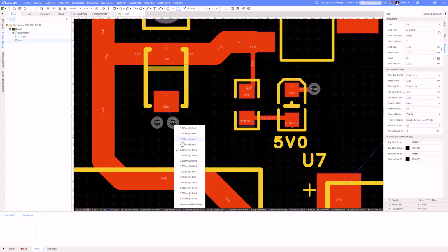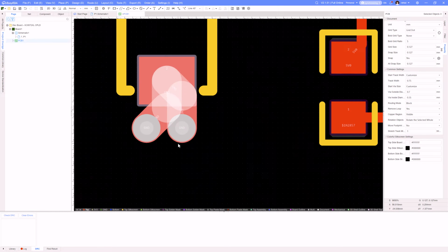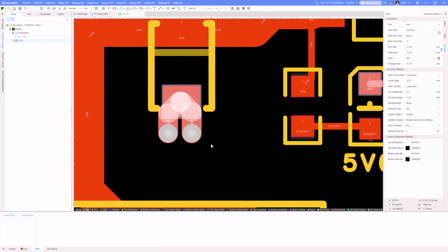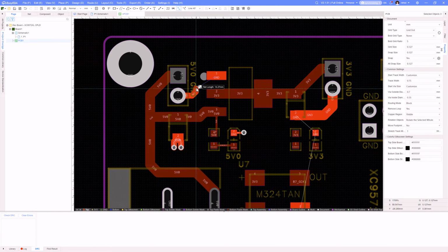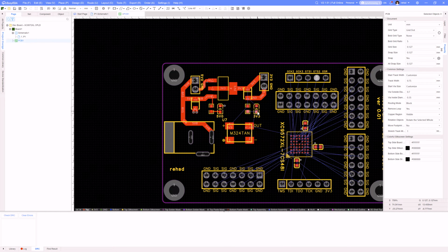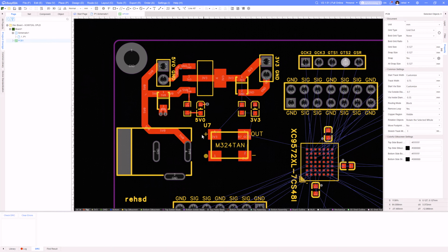Do the same thing, draw a wire, maybe make it a bit thicker. And again, set these however I want to set them, but maybe something like that. Looks like I've got another ground I've got to get connected up here. Now this is a through hole, so that'll get to the inner ground plane there. Also, this is through hole, so these will get to the inner ground planes.